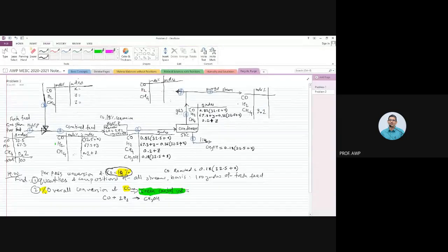Okay, go ahead, Nishan. So X, Y, and Z will go to recycle. You are saying stream number 8 and stream number 2 are identical, so this would also be X, Y, and Z. Yes, and now 0.82 into 32.5 plus X minus X will go in purge. So for the gram moles in the purge stream, stream number 6 is getting split into two streams: stream number 8, which is recycled back, and stream number 7, which is purged.